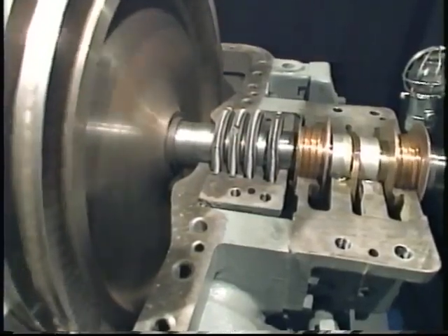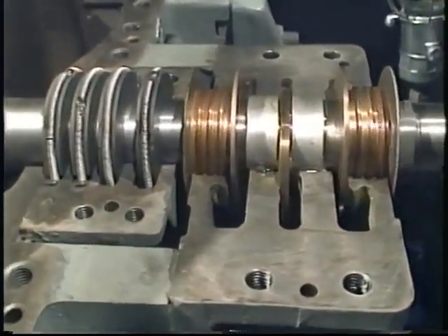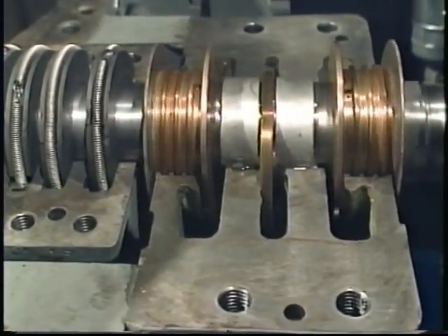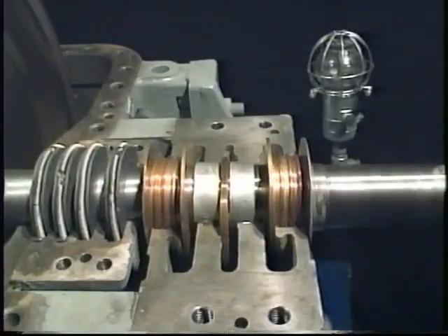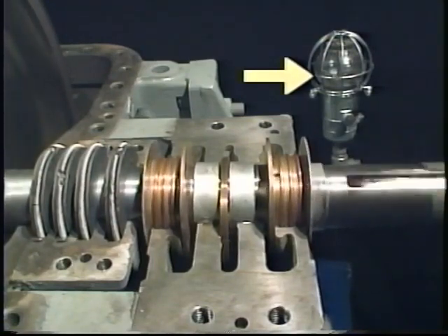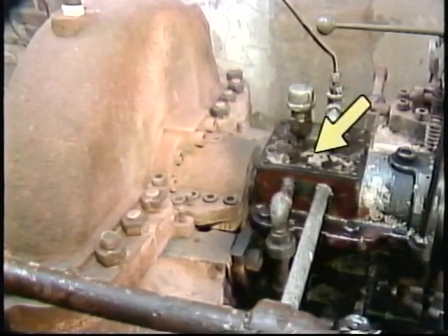In a labyrinth seal, a series of ridges creates an intricate path called a labyrinth. This path makes it difficult for oil to escape and helps prevent contaminants like steam, dust, or dirt from entering the reservoir. In addition, there's a constant level oiler on each reservoir to maintain the proper oil level during turbine operation. For many small turbines, the bearing housings include chambers called jackets that are used with a cooling water system to maintain the oil at the proper temperature.